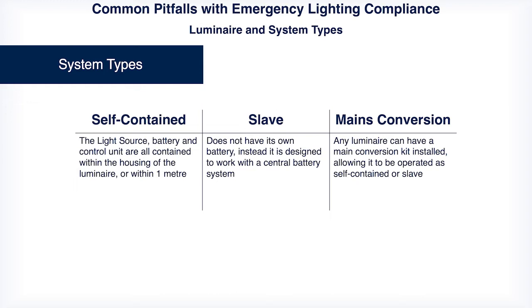And then, of course, there is mains conversion, which can be done where you ask for an LED module that has an integral battery pack, and a percentage output can work in an emergency situation. There are installations across the country where people are adding mains conversion emergency packs with batteries and inverters into an existing luminaire that's already there. It's typically used where there are perhaps failures of dedicated emergency luminaires.